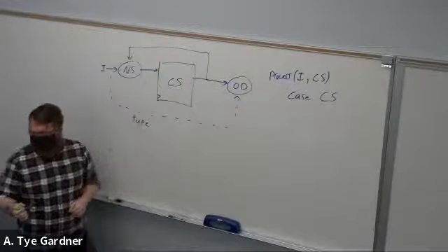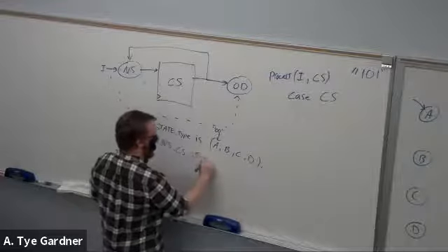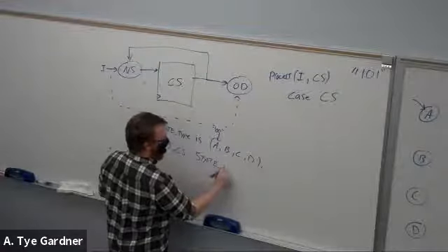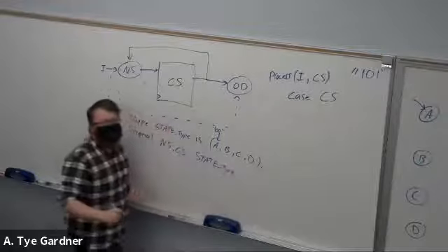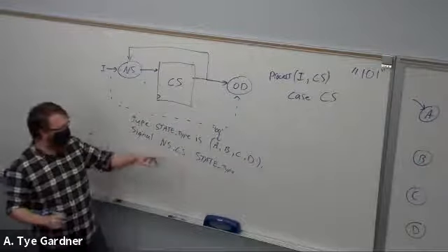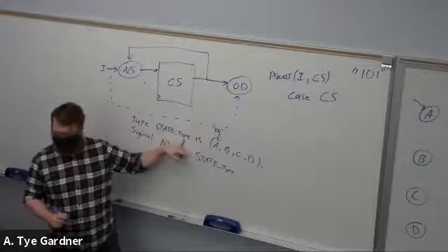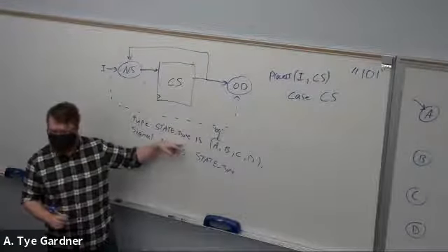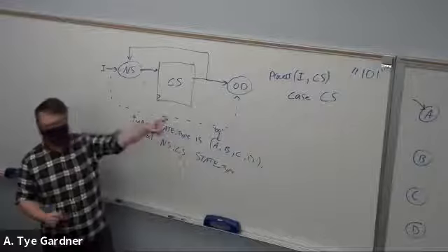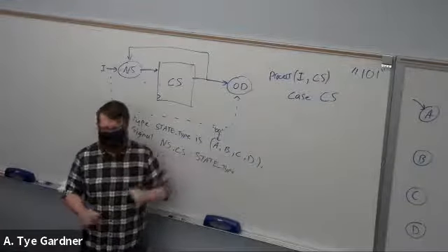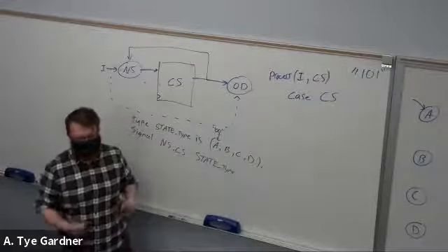But this is just having a type. You don't have any signals that you can work with yet. So you do need to declare signals next state and current state of type state type. This is a mistake that a lot of people make: they try to use the state type as the state variable, but it's a type. So don't confuse that, it happens a lot. All right, so now I've made the signal current state, and it can be A, B, C, or D. That's the only thing it can be. If I do something else, it'll throw an error.